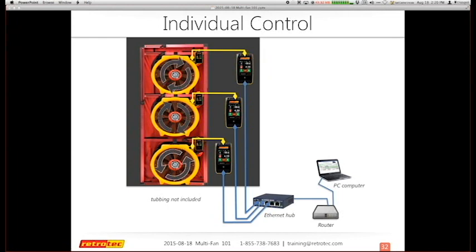So this is actually the dilemma that can happen in a single setup, depending on how you set up your fans in the same structure. Yes, Colin? I just wanted to say that if you set your fans up this way, you can often get away with it, and it can work fine for many, many tests. And all of a sudden, you may not even discover that one of your fans is stopped, because the fan is still spinning, and you may get crazy results.